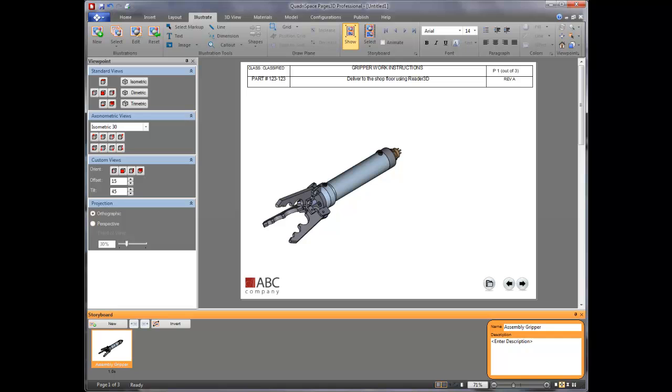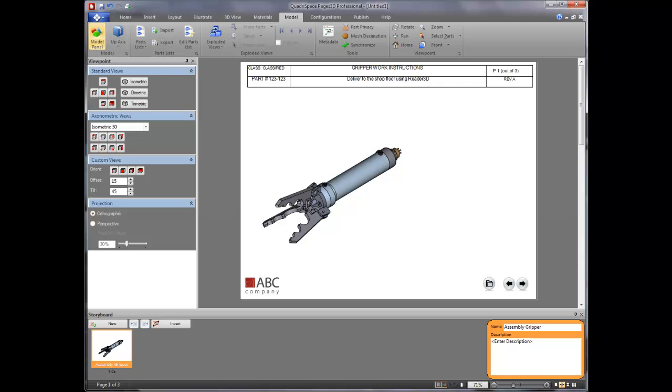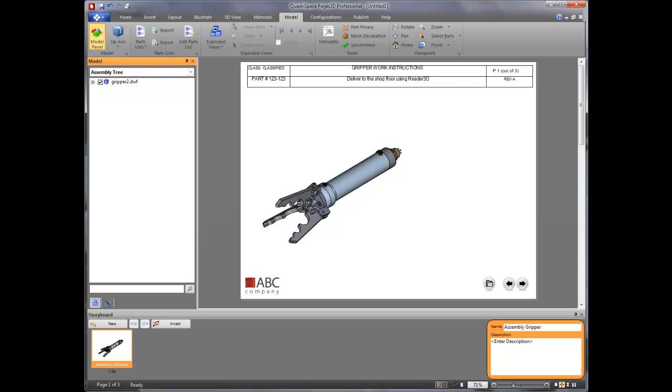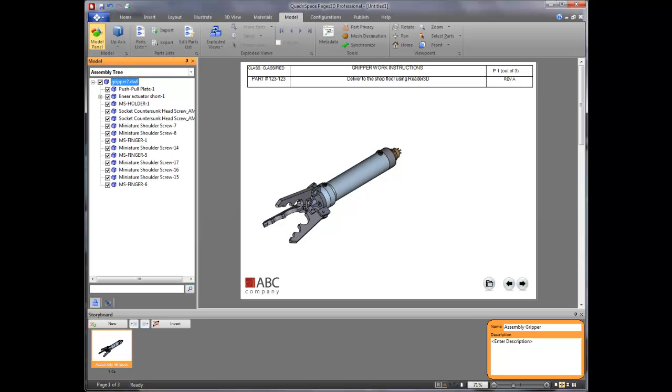Now let's go ahead and create a few configurations. We're going to use these later for our work instructions. One of the best practices for working with large models, this is not a large model obviously, but for working with larger models is to take the model and put it into different configurations so that you can work with subsets of parts along the way. It's really difficult to take a 1,000-part model and do an assembly process using all 1,000 parts at all parts of your process setup.